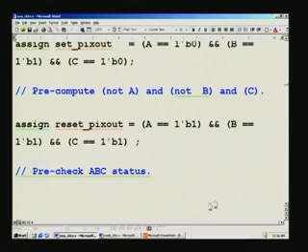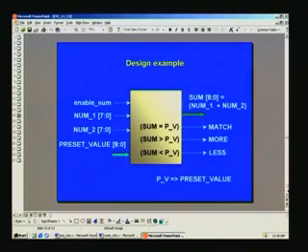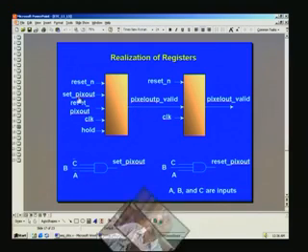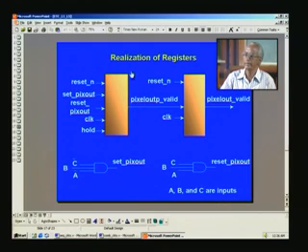And here what we have, two registers we realized in this fashion. When you have just a plain register, which is nothing but a collection of flip flops, say D flip flops, depending upon how many bits you want, and there are reset, set controls, and clock and hold for this, whatever it stores here we want to use only with the arrival of the next clock edge.